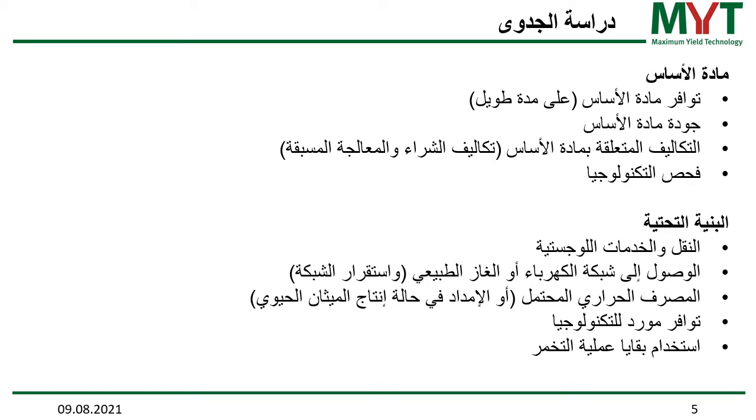Second, the quality of the substrates. Here I'm talking of gas potential, but not only gas potential, also characteristics like the content of total solids or the content of disturbing material, as I already mentioned, sand and stones, metals, plastics, things like that. Make sure that you really have a good estimation or even a good analysis of your substrate's characteristics in order to be able to select appropriate technology.